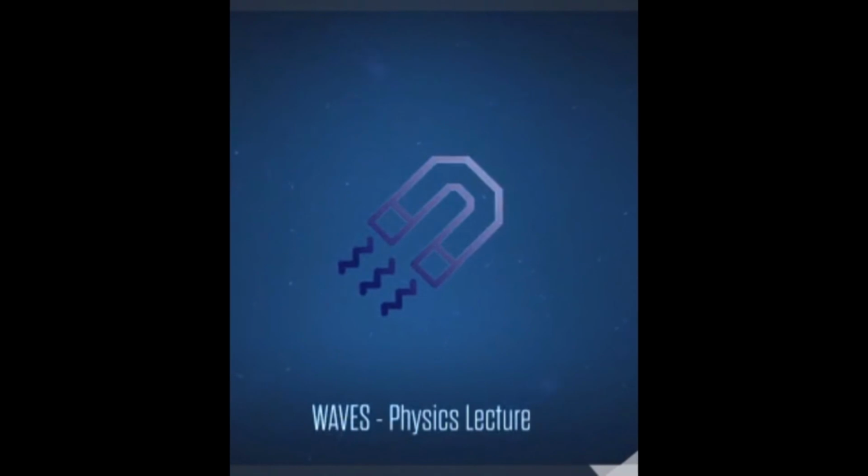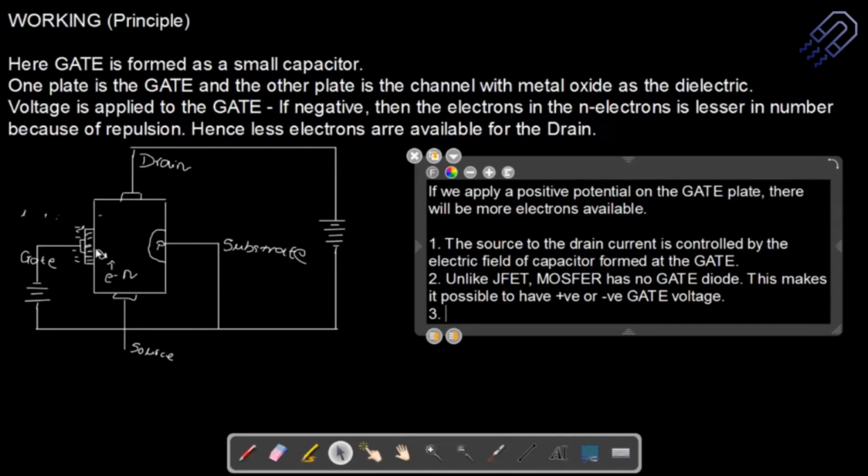Number 3. The gate is forming a capacitor, right? So it will have negligible gate current, whether a positive or negative voltage is applied. Whether you apply a negative or positive voltage, you are not going to have an effect from gate current, because there is an insulator in between. So you are not going to have any signal from this end.